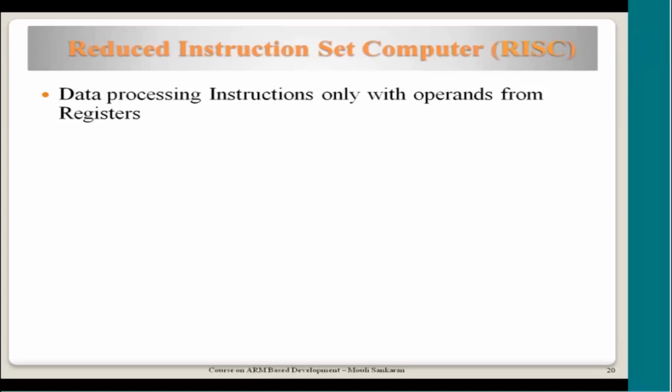You would wonder, how does it reduce the decoding logic of these instructions? If we need to encode information about the two operands in an instruction, and a particular processor gives 16 general purpose CPU registers, we hardly need 4 bits to represent where an operand is coming from. Whereas, if the instructions need to support operands coming from memory also, then we need to say where this operand is in the memory.